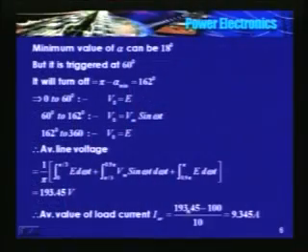So I average is equal to the average value of the output voltage minus E divided by R. So 193.45 is the average value of the output voltage, sorry about that, minus 100 divided by 10 is 9.435 amps.